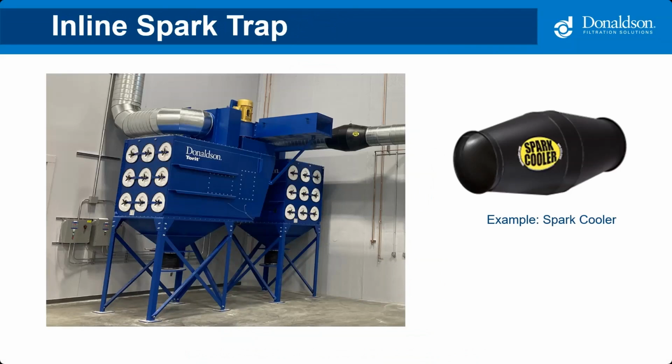Another option would be an inline spark trap, which would be located within the air intake duct, as you can see from this picture. In the image, you see two DFE cartridge collectors sitting next to each other, and the one on the right has a spark cooler, which is the black piece in the ductwork. What that does is create turbulence in the airstream that cools and arrests most sparks without the use of water or chemicals. Let me show you a quick video on the next slide, and you can see how it works.